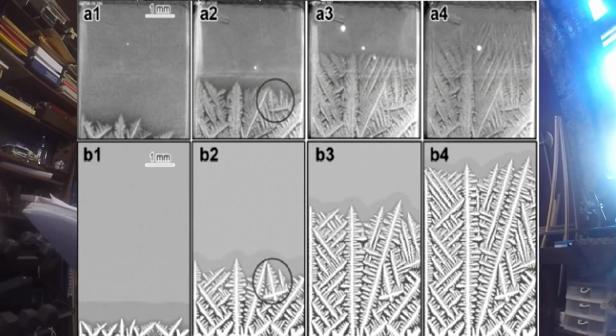Here, photographs have been taken to illustrate the manner in which the growth of dendrites progresses from the relatively cold surface of the mold cavity towards the centerline of the casting, sucking in the molten metal to form the main stems of the crystals and the crossed branches.